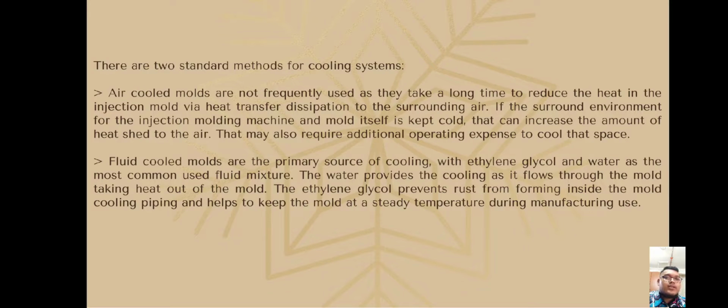And then we're talking about the cooling system. There are two standard methods for cooling. The first one is air-cooled mold. These molds are not frequently used as they take a long time to reduce the heat in the injection mold via heat transfer dissipation to the surrounding air. If the surrounding environment for the injection molding machine and mold itself is kept cold, that can increase the amount of heat shed to the air. That may also require additional operating expense to cool that space.